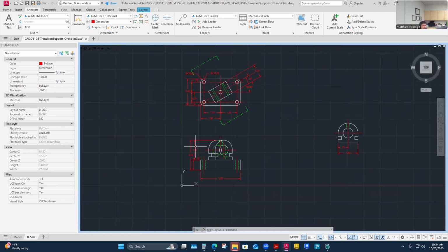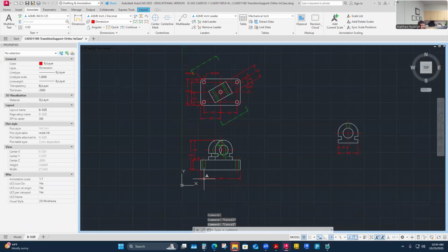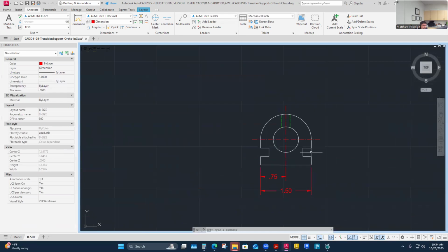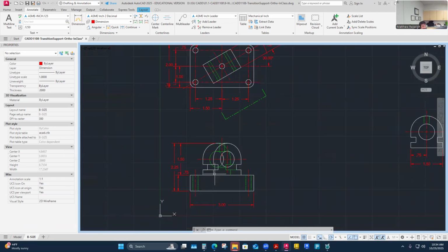And then we can say we're located. Remember, this is another kind of location and size in some ways. So I feel like I've located it in 3 dimensions. Now let's worry about its features of size, which are complicated in themselves. It's got a hole through the top and a hole through the middle, and slots down the side. All this needs to be sized. So let's just take them one bite at a time. The only place to size the slots is in this view here. Everything else has some foreshortened aspects of it, or hidden lines that I don't want to dimension to.